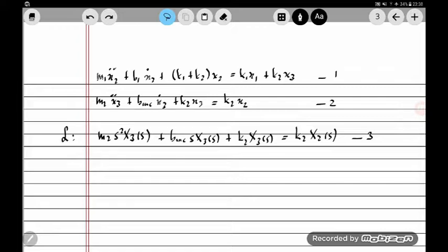Before I continue drawing this detailed transfer function block diagram, I want to point out something important. It's convention to avoid using improper transfer functions in a block diagram. If you recall, an improper transfer function is one in which the order of the numerator is greater than the denominator.